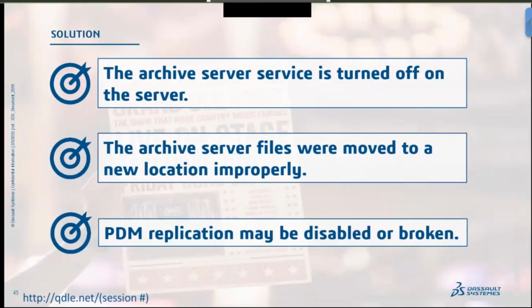Well, they don't realize that that data was actually being controlled by a database at the same time. So now this database thinks all these files are in that first location, not knowing that they were moved somewhere else. So with all the best intentions, IT is trying to save us some space and make sure that things are working properly, but it's temporarily broken our PDM system because we didn't tell the rest of our PDM system where to look from here on out. So that could be something that we run into.